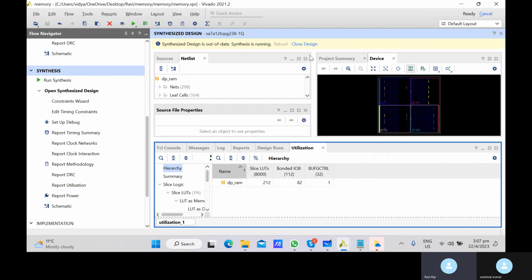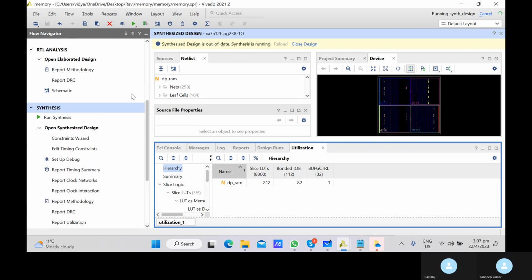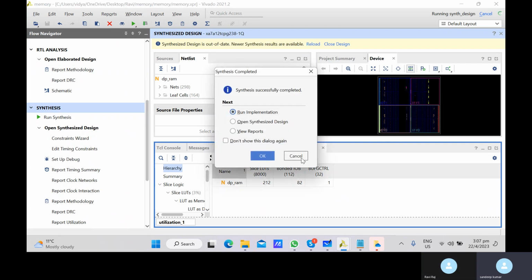Based on the memory type, we are just modifying our code. Based on the code, basically you can say we generate the memory, or for a given type of memory, there is a certain coding style. In future, when you become an FPGA engineer, you want to optimize the usage of FPGA. You must know where to put your logic, in the RAM or the distributed RAM.